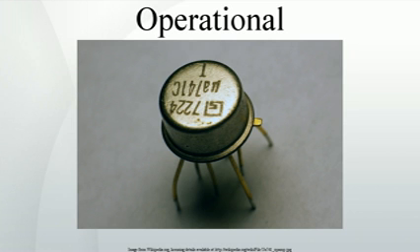1949, a chopper-stabilized op-amp. In 1949, Edwin A. Goldberg designed a chopper-stabilized op-amp. This setup uses a normal op-amp with an additional AC amplifier that goes alongside the op-amp. The chopper gets an AC signal from DC by switching between the DC voltage and ground at a fast rate, 60 Hz or 400 Hz. This signal is then amplified, rectified, filtered and fed into the op-amp's non-inverting input. This vastly improved the gain of the op-amp while significantly reducing the output drift and DC offset.